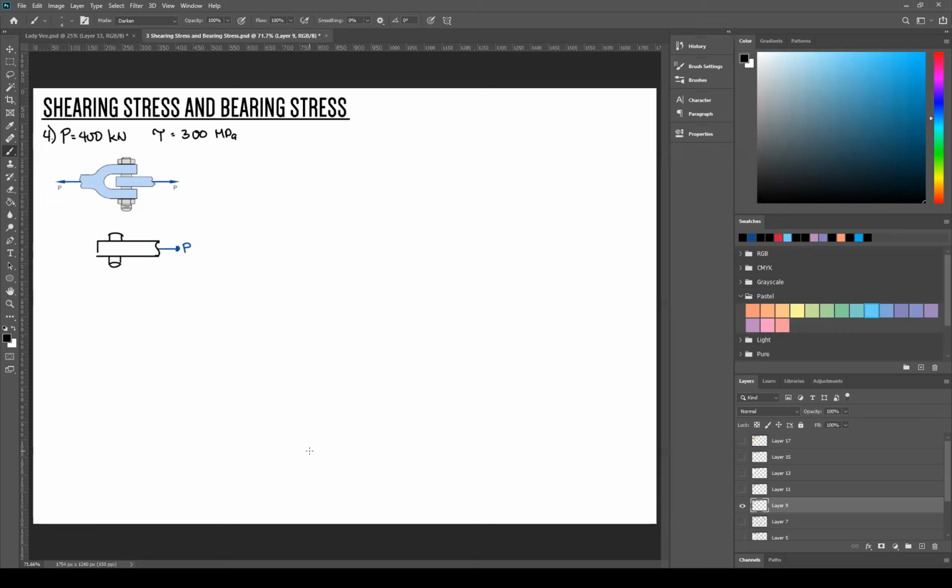So there. And again, wherever you cut, that is where internal loads will be. There's a cut here, so there's an internal load here, and then another internal load. And by now, you should have understood that that internal load is the shear force. So V. Therefore, summation of forces equals 0, negative 2V plus P equals 0. V is just P over 2. Okay, now you have, and P is 400. Now you have an equation for V.